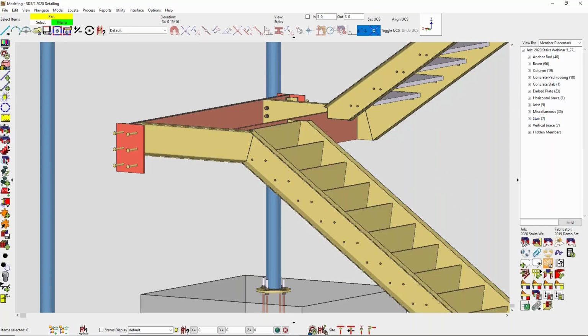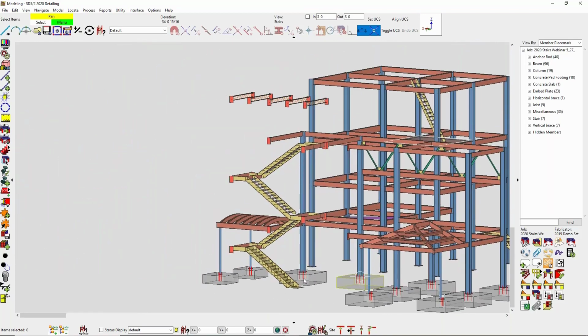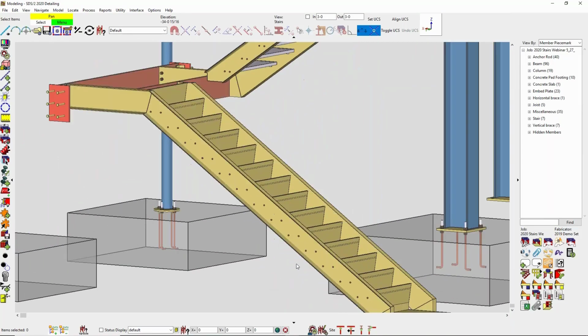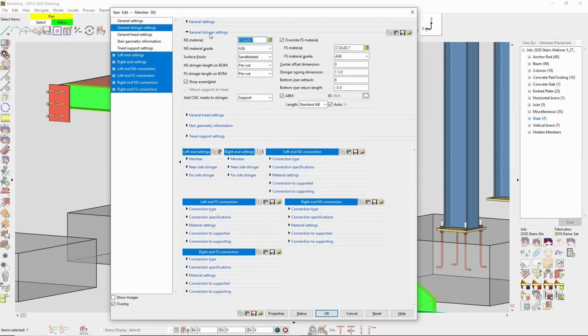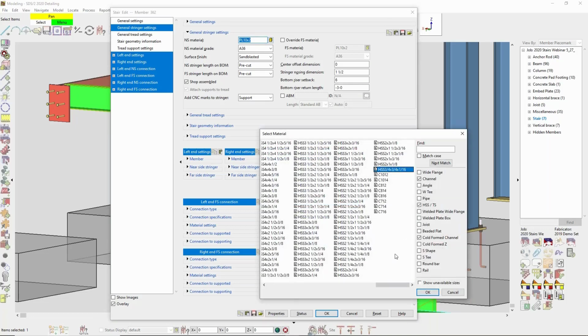Oh, I'm still in the estimating. All right. Yes. Can you put in plate for your stringers? I think I had that one in my other example. Yes, you can put in a plate for your stringers. So if I edit this, I can come in my plate stringers, and I can type in a plate. I don't really know for anything right now, but 10 by, I don't know, 2. So you can add in a plate here. Even though it's not in your material file, you can go ahead and override that and put in a plate for your plate stringers.